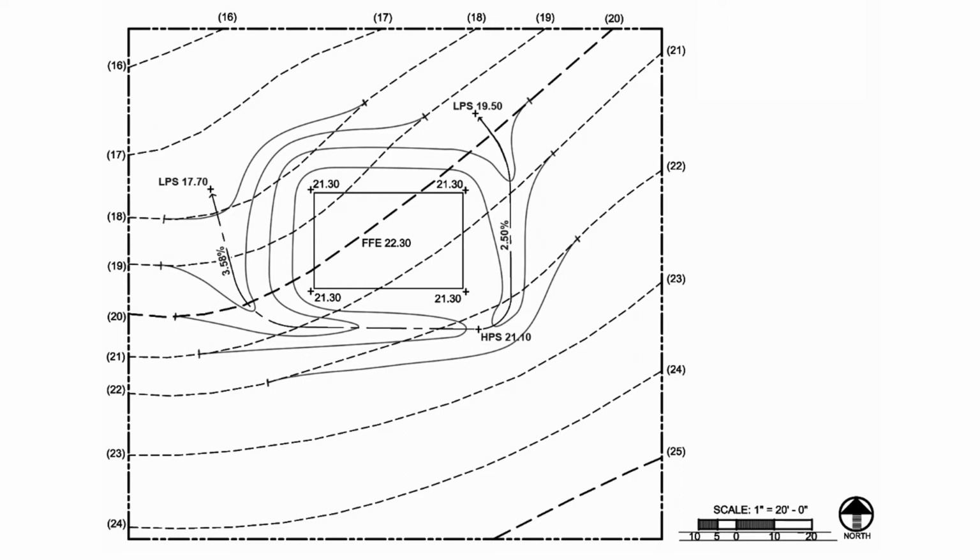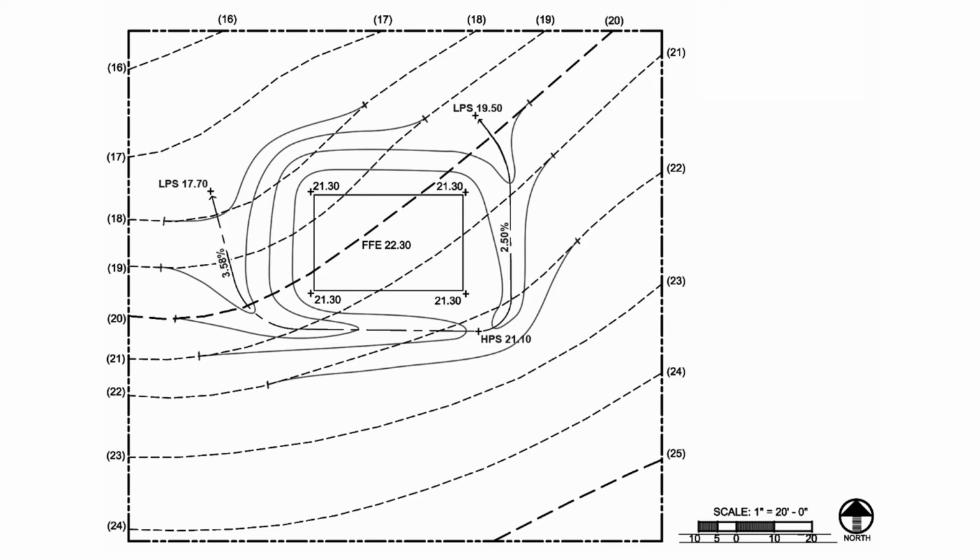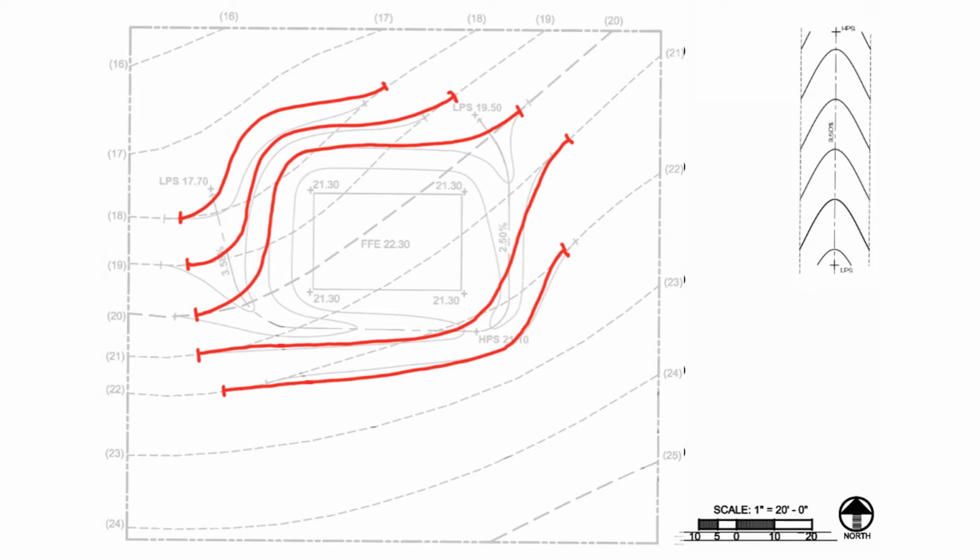So this is what a swale around a building can typically look like in terms of the contour pattern. And if you remember from the grading the terrace methods, the red contour lines here represent the balanced method for grading a terrace, right? Also, if you remember from the grading the swale method, a stand-alone swale has a V or U-shaped contour pattern, right? Now, if you look closely, can you see that the pattern we're trying to learn today is indeed a combination of these two?